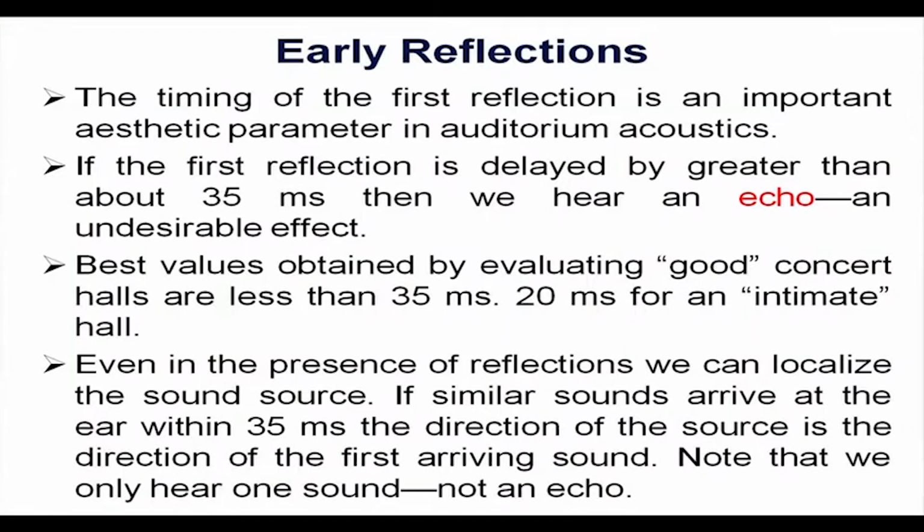The time of first reflection is an important aesthetic parameter in auditorium acoustics. If the first reflection is delayed by greater than 35 milliseconds, then what will happen? Echo will come, which is not desirable for an auditorium. So, first reflection must be within 35 milliseconds.